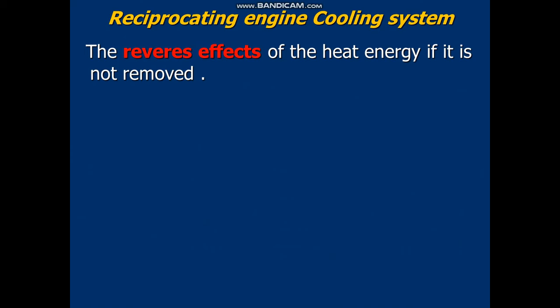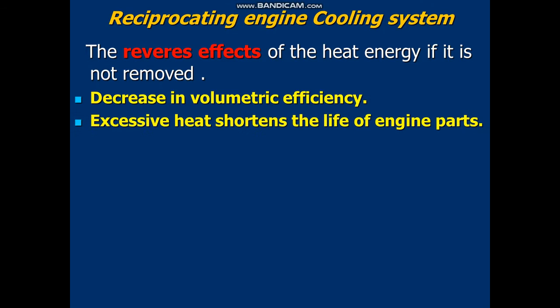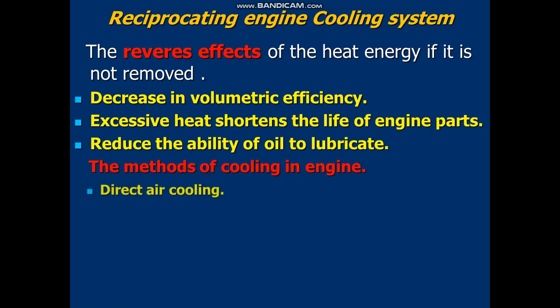The adverse effects of heat energy if it is not removed. The first thing, decrease in volumetric efficiency. After that, excessive heat shortens the life of the engine parts. It also reduces the ability of oil to lubricate. The methods of cooling an engine: direct air cooling or liquid cooling.